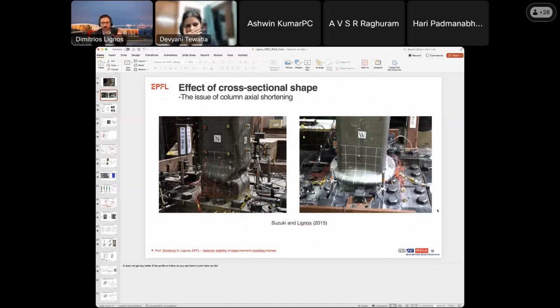The axial load ratio would be close to maybe 5 or 10%, so you would easily meet the limit. For web slenderness, you may go near the compactness limit, so there I would be a little careful. But if the design is not governed by something else, I think neither will control for a low-rise building.